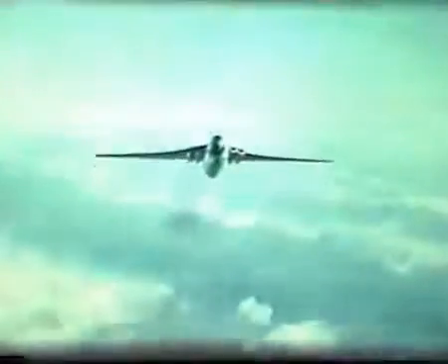The other important way of raising the critical Mach number is by the use of sweep back. To understand this, let's look from above at the flow over a wing. The contour of the wing section determines the amount the air is speeded up. Now sweep the wing back. We can represent the velocity of the airflow ahead of the wing by an arrow of a certain length. We can consider this velocity as made up of two smaller components. A yellow component at right angles to the leading edge, and a red component parallel to the leading edge.